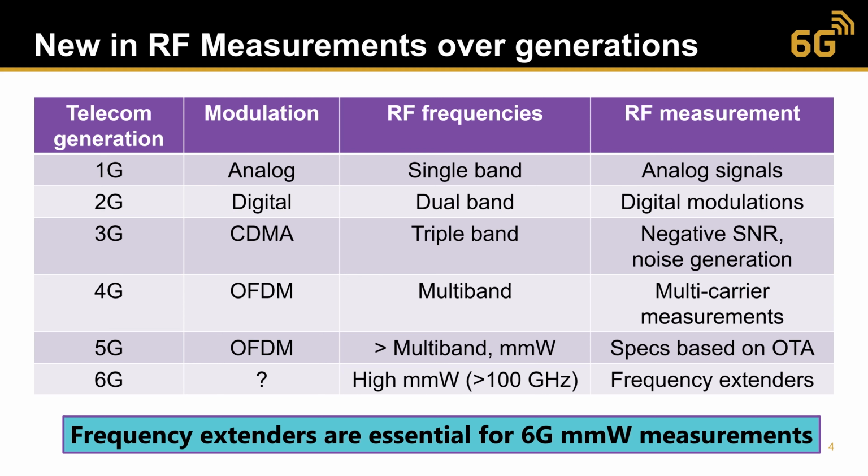The 4G changed the modulation to orthogonal frequency division multiple access, or OFDMA. OFDM spreads the communication signal in the time domain and frequency domain at the same time. Such a signal reuses blocks distributed over multiple subcarriers, and those lead to an increased peak-to-average power ratio, or crest factor. The 4G systems were deployed at previously operative frequencies as well as new frequencies, thus leading to frequency support expansion in mobile and base stations as well.